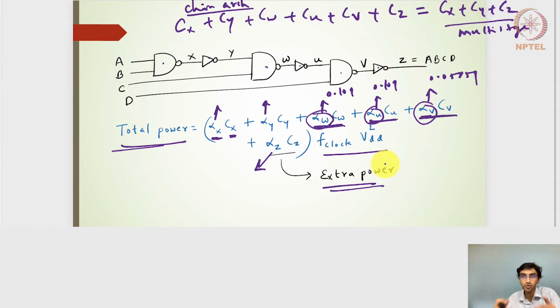So having more nodes or more stages, especially in the chain architecture, although it gives me the same logical expression, I might still have extra power. This chain architecture is going to dissipate more power, or the VDD rail has to deliver more energy, for the chain architecture.